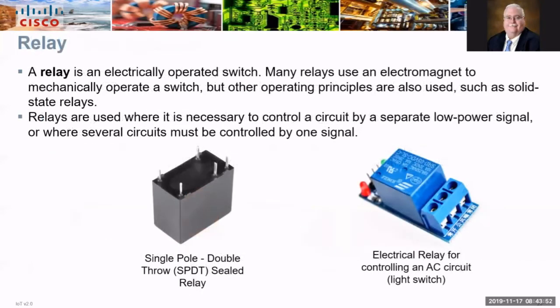A relay is an electrically operated switch. Many relays use an electromagnet to mechanically operate a switch, or solid-state relays. Please note, the relays we use in the lab do not fit the breadboard very well. I suggest you solder a short solid core wire to each of the 5 terminals to facilitate a better connection.